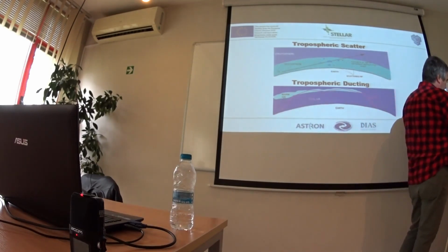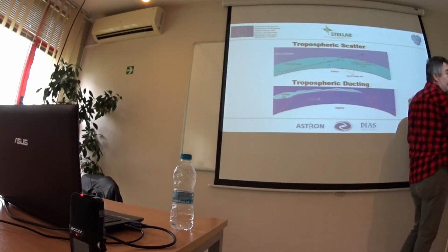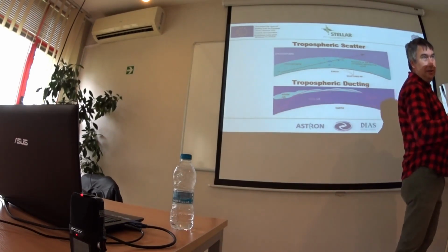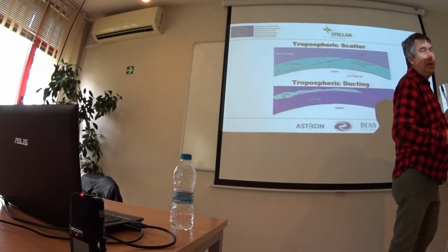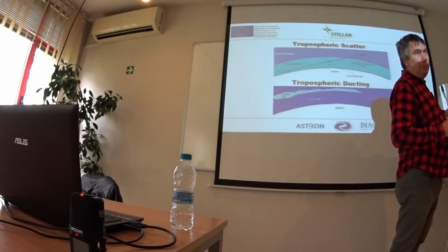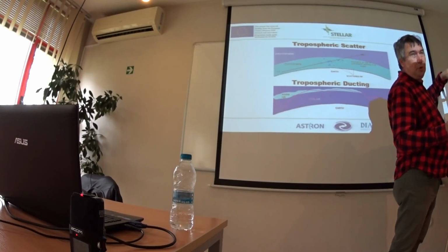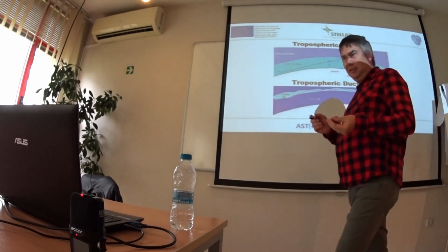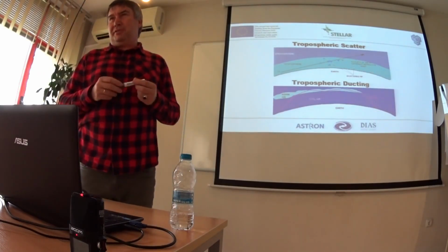So we transmit a signal, it reflects from this, then from the sea surface, then again, and we have a waveguide from the sea and this layer with high humidity over sea level. And this causes propagation over very big distances.